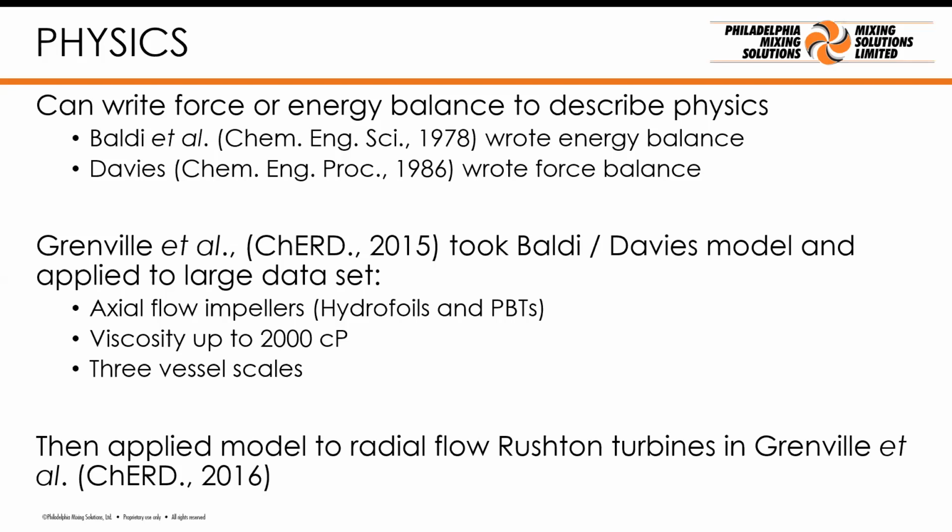And so I and my co-authors took the Baldi Davis approach and applied it to a really, really large data set: 3 vessel scales, viscosities up to 2000 centipoise, water-like to 2000 centipoise, for hydrofoils and pitch blade turbines. And the following year, we then applied this same model to radial flow impellers, the Rushton turbines.